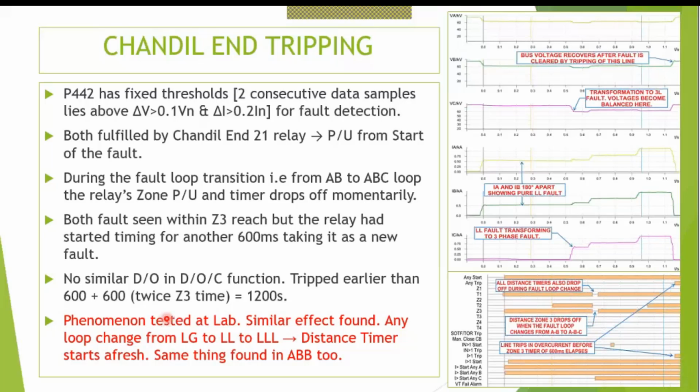And it was tested in the laboratory, and a similar effect was found. With any loop change from LG to LL to LLL, the distance timer was starting afresh in the Areva relay. The same thing was found in the ABB relay too. Siemens I have not tested, I've forgotten Siemens. Probably I'll do it and let you know.